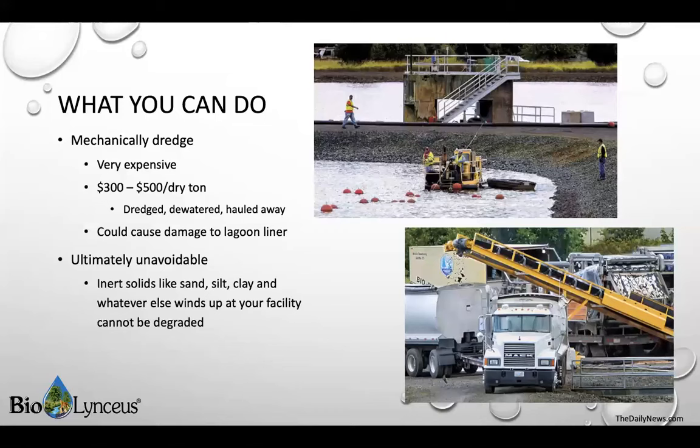When it comes to managing your solids, there's a couple things you can do. Many mechanical plants have the option of wasting sludge at their leisure. That is, sending it to a digester before ultimately processing it for secondary applications. Some mechanical plants utilize sludge holding ponds, but either way, the sludge will need to be handled. Lagoon treatment facilities don't have the luxury of being able to waste sludge. For these facilities, handling sludge is a constant battle.